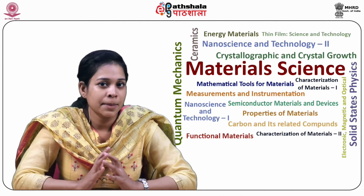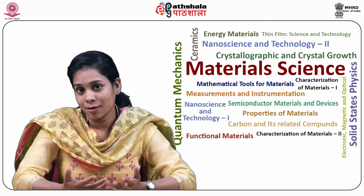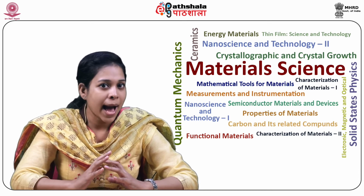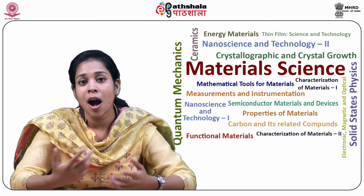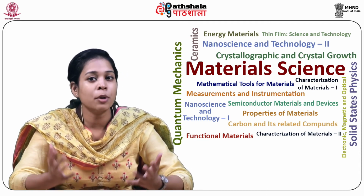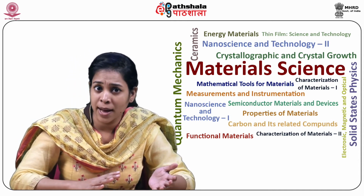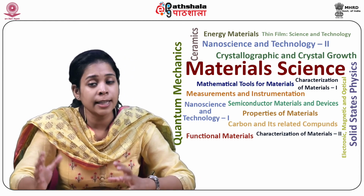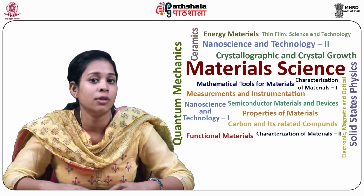So now comes packing of atoms in metals. In solids, we consider atoms as hard incompressible spheres which can be packed in various forms. So first we will see how atoms pack in metals. Atoms in many metals form close packed structures either in the form of hexagonal close packed structures or face-centered cubic structures. Face-centered cubic structures are where the atoms occupy the faces of the unit cells.